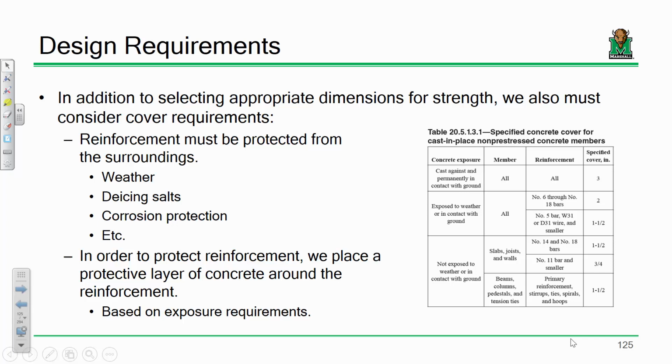For instance, if I'm talking about some mass of concrete and here's a piece of rebar in it, cover is that dimension right there, or that dimension right there. In other words, how far must I embed that piece of rebar into the concrete? First off, we have limits for really two reasons. We want to make sure that the rebar is far enough in the concrete so that we get the strength out of the rebar that we would like. That's obviously an important reason.